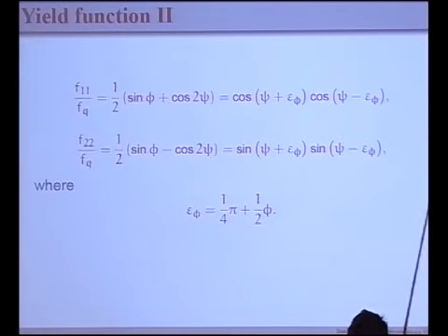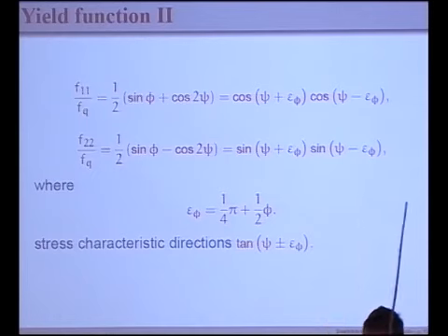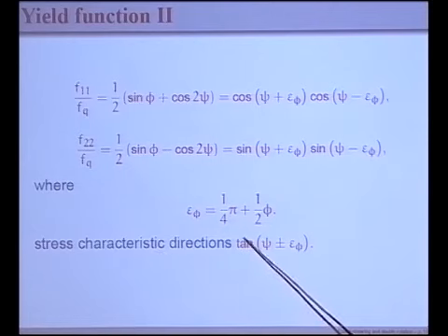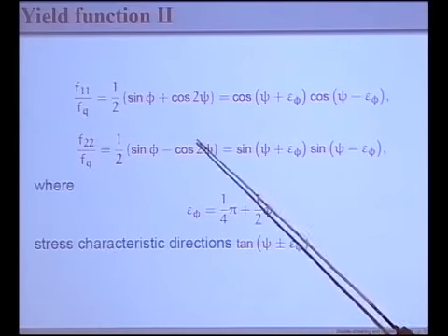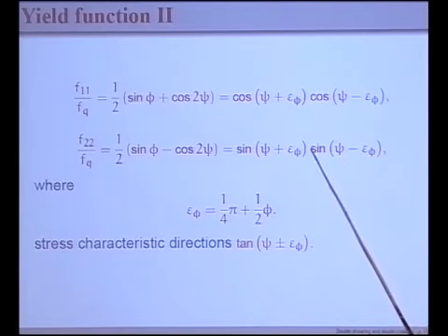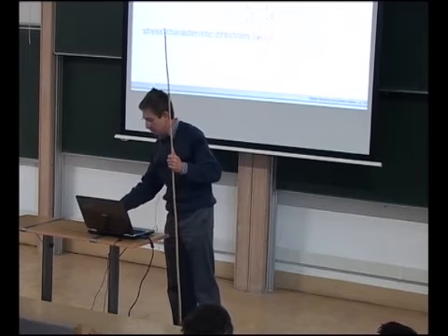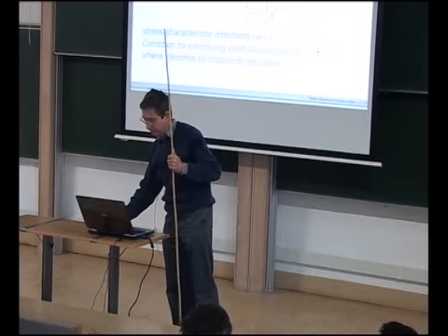This transparency here is to show that indeed the well-known characteristic structure is contained in this second order tensor Fij. And if one were to do characteristic analysis, then indeed the stress characteristic directions for the stress equilibrium equations and the yield condition would be given by this.